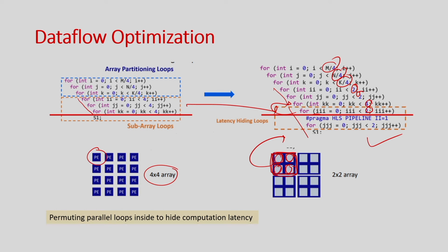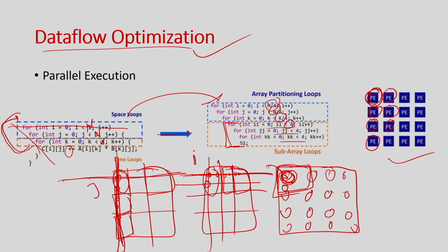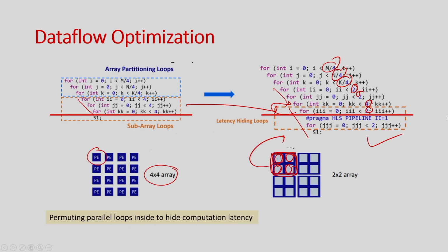So, with this, what I can achieve here, the whole purpose of doing all these things, is basically to parallelize these calculations of matrix multiplication for each element, right. For each element there are n multiplication operations, and how to parallelize them and execute them in parallel, right. So, that is the idea, and this is how we can modify the code, and then you can apply this dataflow optimization there, and you can actually get a great performance benefit. Okay. I do not go into the synthesis result, but you can always try this and see the benefits of doing all these things.